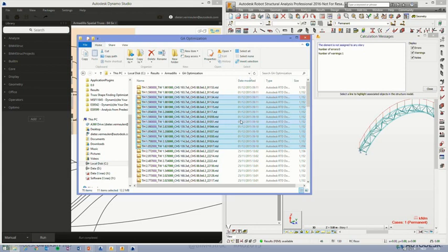What it has done now at this moment, this is the population which we will use to start. So those are the first elements in the optimization. Truss height 1.8, truss width 1.6, and the section index, well, I will use some rounding to find the lowest integer, so it will be section index 1. And these values are the weight scores, so it's a placeholder. So of course I didn't do any optimization yet, so I don't have weight scores, so those values are equal to 0.